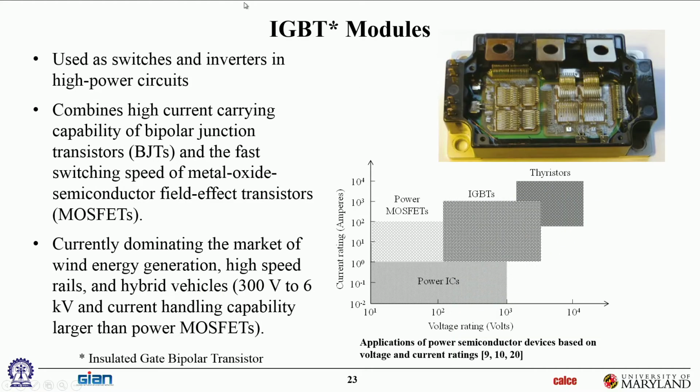Okay, IGBT modules, they have their own problems. So that stands for, the acronym is given over here, insulated gate bipolar transistors. Remember we talked about bipolar transistors and field effect transistors. The problem with classical bipolar junction transistors is that the switching speeds tend to be low. So here with special insulated gate technology, they're able to get pretty high switching speeds at very high currents and voltages. So that's what IGBTs are used for, as high-speed switches in electronics for converters, inverters, and other technologies.